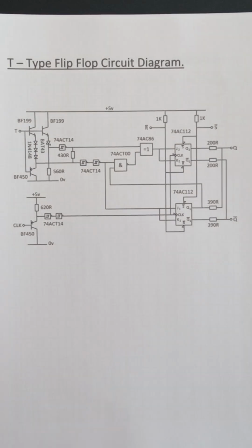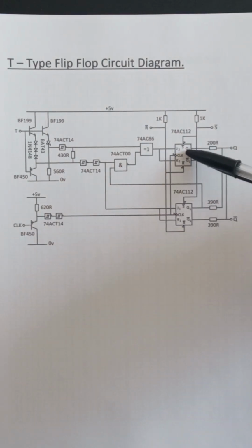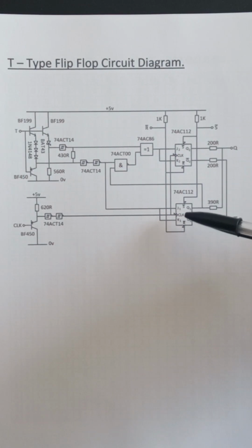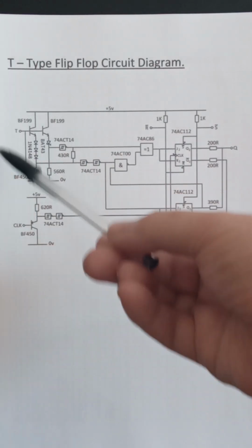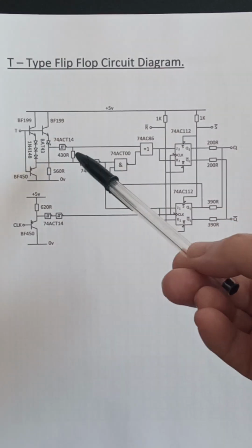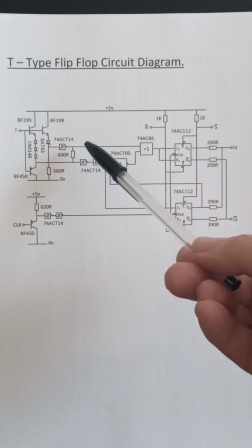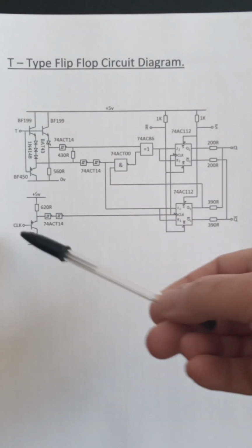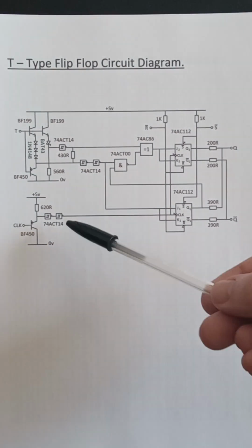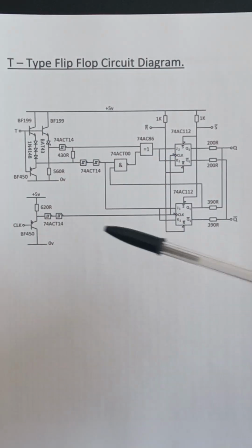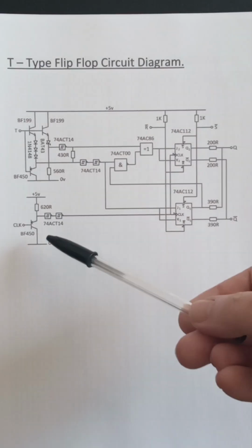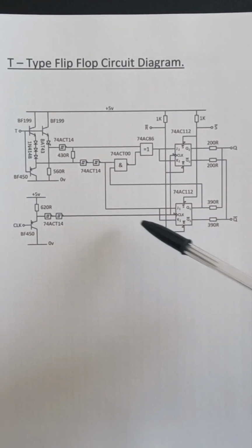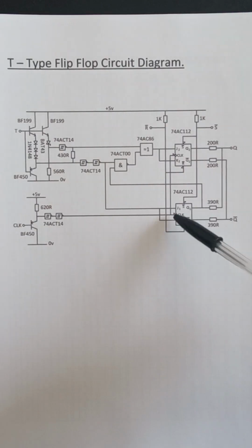So here we have the flip-flop circuit diagram for the Quaternary version. Here we have the JK flip-flops, the Quaternary to binary conversion for the T flip-flop for input T, clock here, which provides these clocks to the flip-flops on a negative going edge from a quaternary logic 1 to quaternary logic 0, and that feeds the clock.